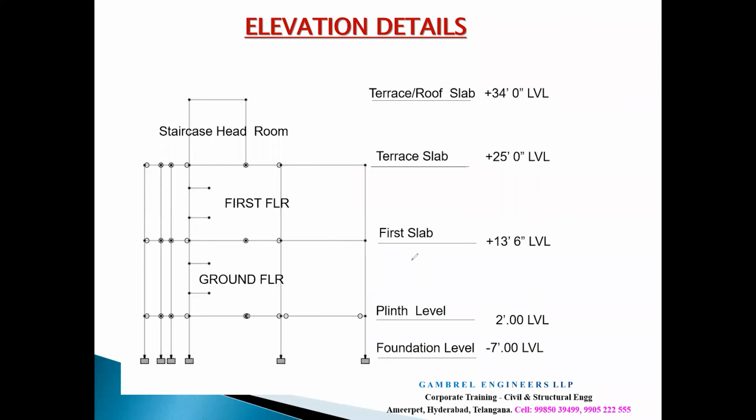So why did we consider only 11.5 feet, right? Technically, some people can also go for 11 feet. Some people will go around 10.5 feet. But going less than 10.5 feet floor height is not recommended, because there is a slab thickness and there is also a fan height, and then we have a cot height. And if you just stand on the cot, you should have enough space.